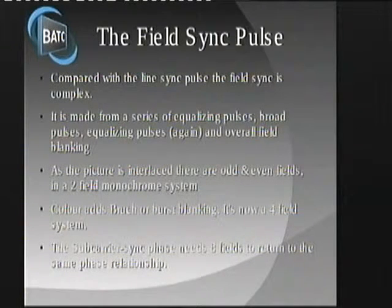In a monochrome picture, because it's interlaced, there are odd and even fields, so you need two fields to get back to where you started from. When you add in colour, it gets more complicated. Because the phase of the burst is such that it changes from one field to the next field to the next field to the next field, you've got to go through four fields till the phase of the burst is the same as it was.